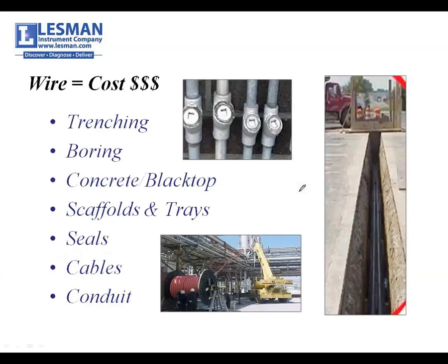When you look at costs, physical things related to wiring, you'll recognize up here in the middle these explosion-proof seals. All these things are expensive. The piping is heavy and expensive. If you have to go through a parking lot, you're looking at trenching, boring, removing blacktop, things that get costly quite quickly. And of course, cable trays, conduits, all the miscellaneous parts that we're virtually eliminating by going with a wireless strategy.